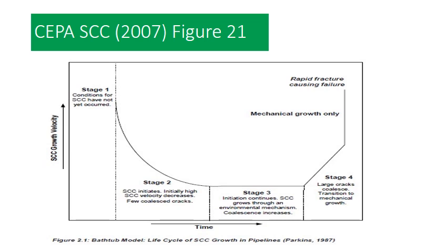People will look at the electrochemistry, the phenomenon that's going on at the crack tip, and how the chemistry is affecting crack growth. People will talk about hydrogen ingress and diffusion, hydrogen concentration at the crack tip leading to embrittlement of the material. You'll hear about anodic dissolution. Some people will tell you that as the cracks get deeper, there's a longer diffusion path for species to move along, which slows down the whole reaction rate and cracking mechanism. And you'll hear people talking about deeper cracks transitioning to more of a fatigue type behavior, which increases their crack velocity.